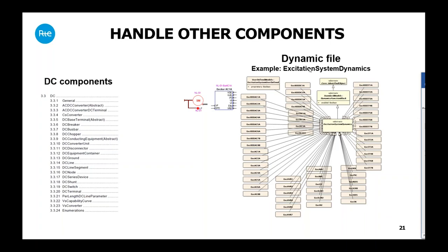But the dynamic profile is divided into two categories in the CIM. We have standard models and user-defined models. User-defined models support the exchange of proprietary models and also elementary control blocks. And this is complex, and it's not handled yet in the interface.